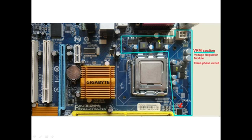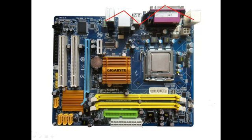There are several components present in the VRM section, like transistors, coils, capacitors, and an IC, which we call a VRM IC. This VRM IC is sometimes referred to as PWM IC or oscillator IC or regulator IC. Here 1, 2, 3 coils are present, which indicates that it is a 3-phase circuit.